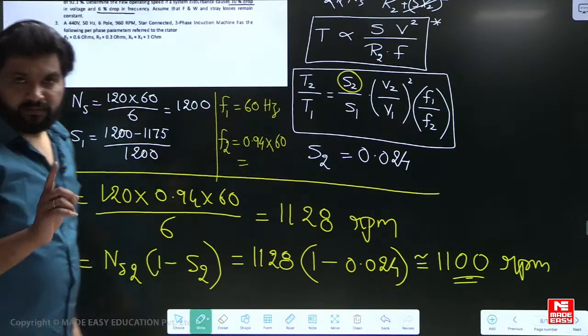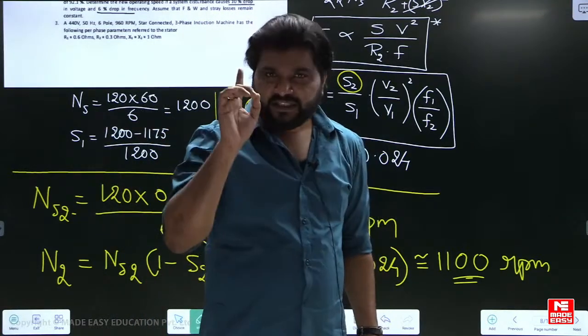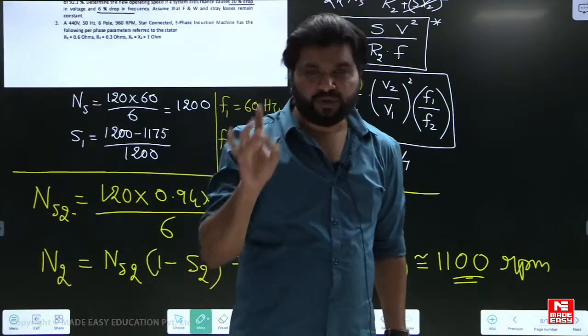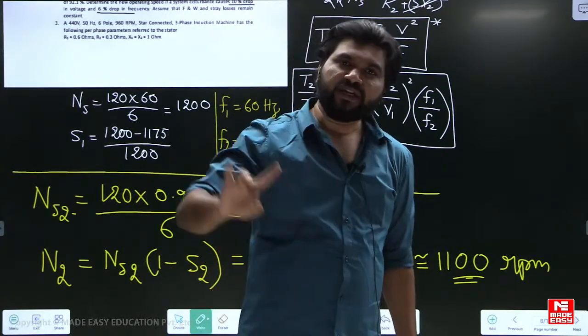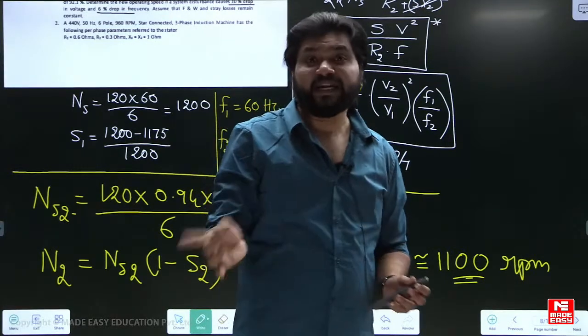Yes, Ns2 will change. You have to remember this because there is a change in frequency, so there is a change in synchronous speed for sure. If there is a change in synchronous speed, accordingly N also will change. So remember that for the new frequency, what is Ns?